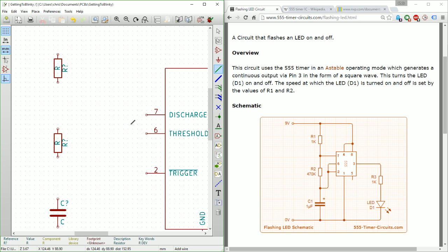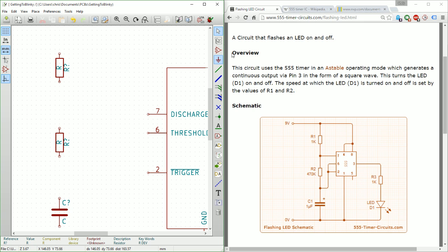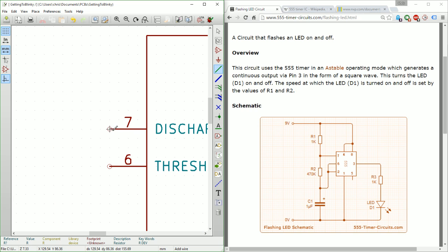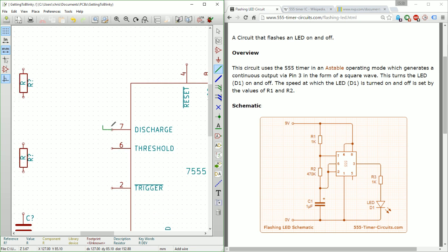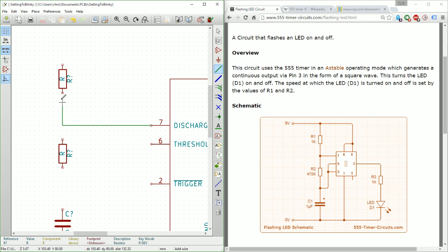Now if I want to start drawing a trace, I can click over here on the green line, which is place a wire, or I can hit W, which is what I normally do, to start drawing a wire. Now you'll see I did that right over top of this node here, and I am just scrolling in using the mouse wheel. So what I'm going to do is go to this point, take it up here, and click on top of the node, and you should see that circle disappear.